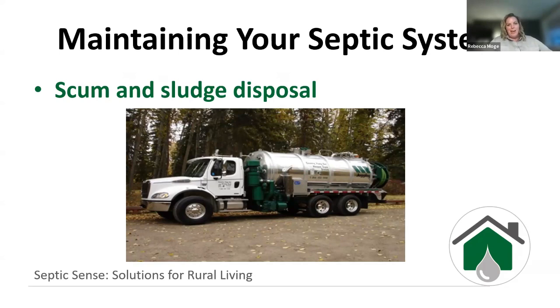Sludge disposal. So we have an example of a vacuum truck here, a suck truck. When you have the suck truck out, if it sounds like it's sucking gravel, it's potentially our concrete tank starting to fail. So we might want to start saving for a new one. We've got, just behind the cab there, the green portion is the discharge portion, and it works just like a vacuum in our house. However, we don't want to be standing in that area. It's quite odorous and things like that.